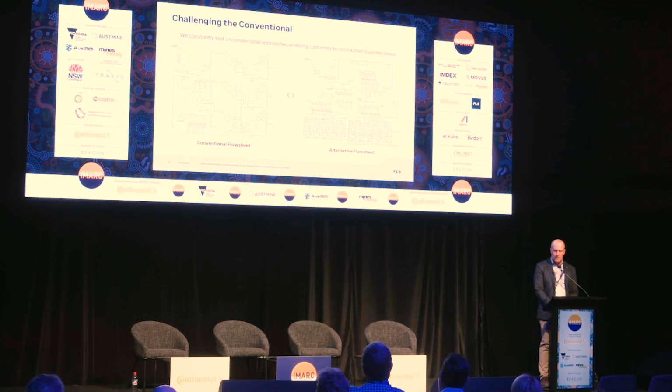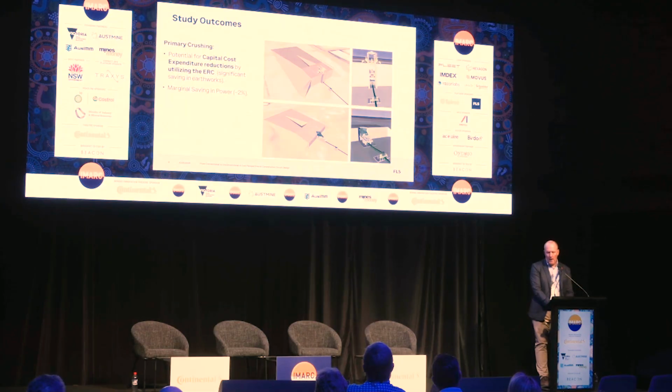We compared that to a circuit which contains an ERC as the primary crusher, your conventional cone crushers as your secondary crushers, going into 4 HPGRs, and then eventually into 10 tower mills. We needed the 10 tower mills to get us the capacity, but it still turned out to be a significant number of equipment to do that.